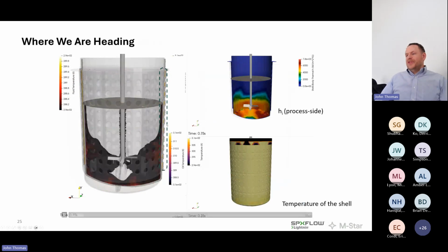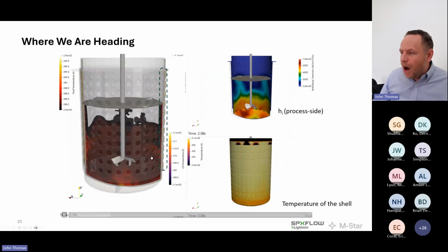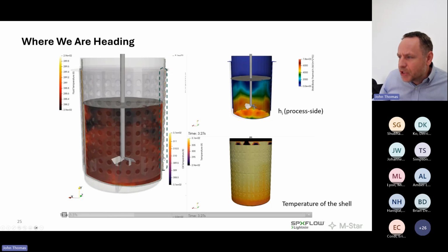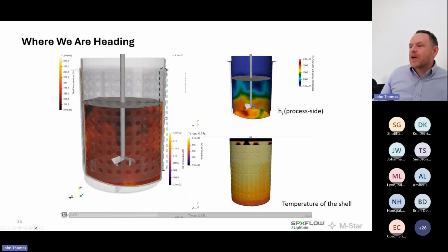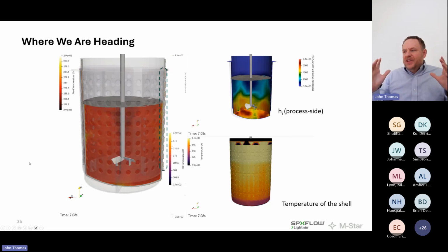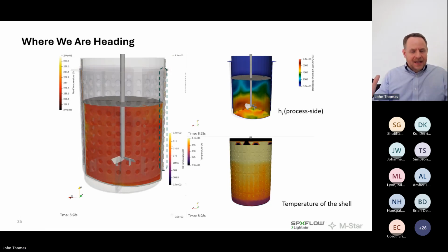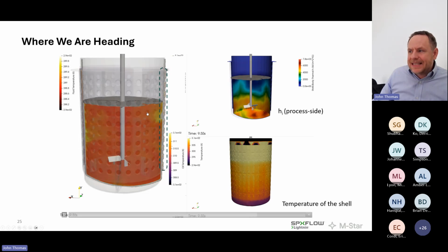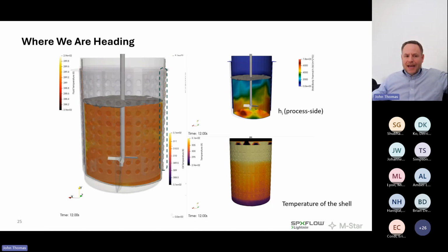And so what we can do with this now is we can actually start to model both the time evolution of the temperature inside the jacket and the corresponding time evolution of the temperature inside the fluid. Recognize that this is the whole thing. We're predicting the time evolution of the temperature at a probe inside this vessel as a function of the flow rate of the oil going through the jacket and thermophysical properties. That might be, I'd say, jacket topology and thermophysical properties of the fluid.